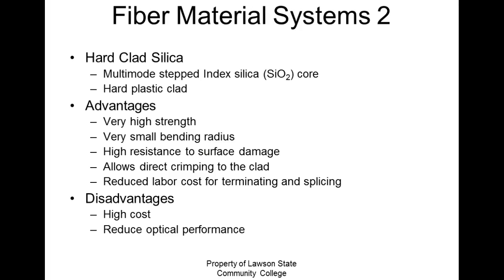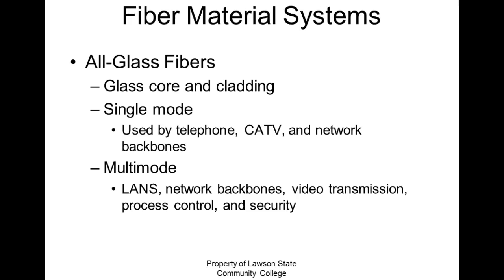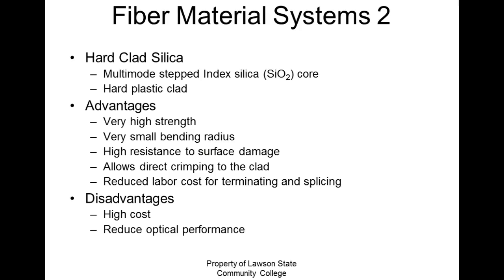So hard-clad silica, that's what we use. Multi-mode stepped index. All glass, that's what we're using. It's using hard-clad silica fiber. It has a glass stepped index core, and it has a hard plastic clad. So this is going to be cheaper, but it's going to have a lower bandwidth product, right? You understand that?